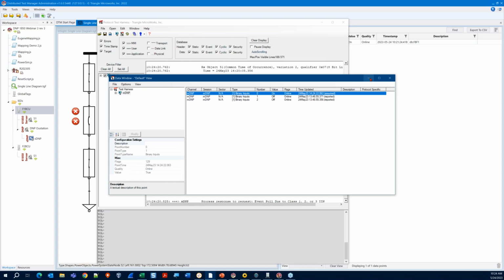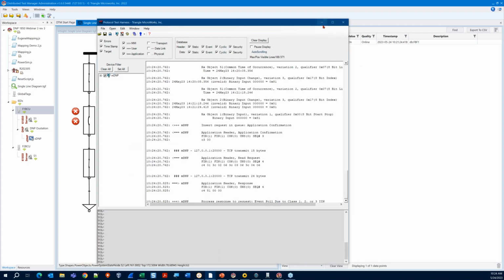And with that, we've demonstrated what it would look like to have a multi-protocol device with both 61850 and DNP, and how that could be used in conjunction in a basic way. GOOSE to replace our wires, but still holding on to DNP to pass information up to both our local HMI and SCADA. And with that, I'm going to go ahead and pass it back over to Christoph, who will continue with slides.